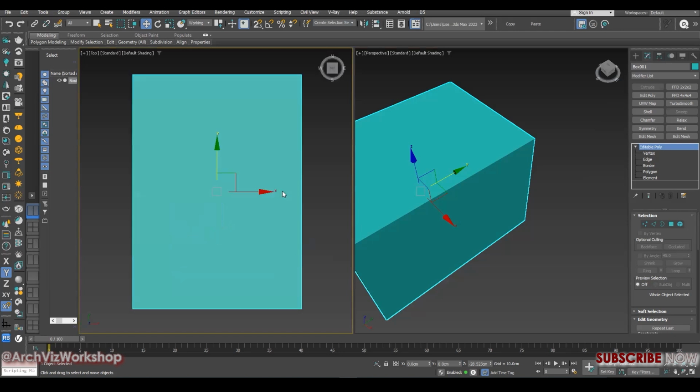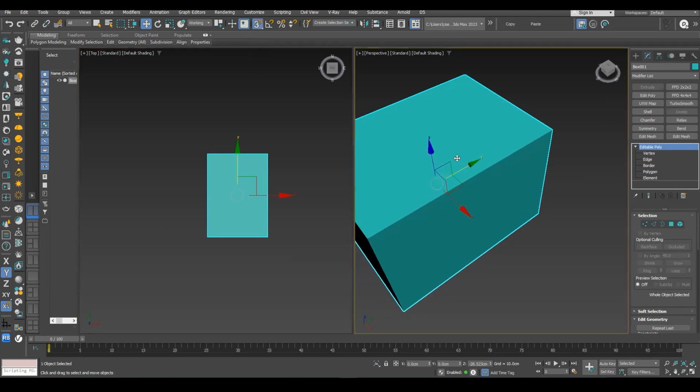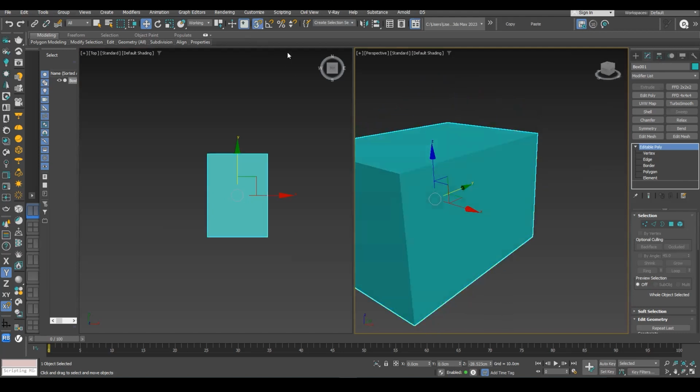Okay, and then I want to share the snapping tool, the snapping toggle. Click here, give some point and click, and give some point over here. You need to find here 2, 2.5 and 3. So 3 means when you work in 3D perspective, you need to activate the 3 snap.